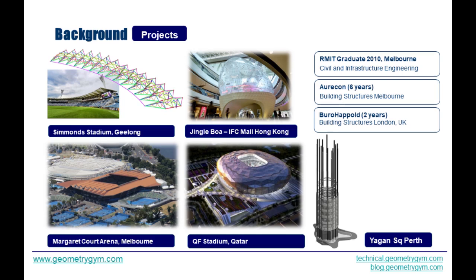I worked on Mark Arena coming out of university, and I did that the hard way in terms of how you build geometry in a structural analysis model, trying to get wind result data from Excel into a Space Gass model, which took me a month. Whereas now I could do it in a couple of minutes and update it as things change.